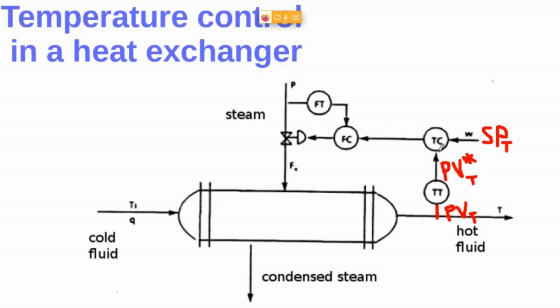So this voltage is compared with this set point, right? And then we have the error, the control error inside this temperature controller. This will be the manipulated variable for the temperature. And here's this signal. As you can see, this manipulated variable, because it's the output of the controller, comes as the set point of an inner controller.